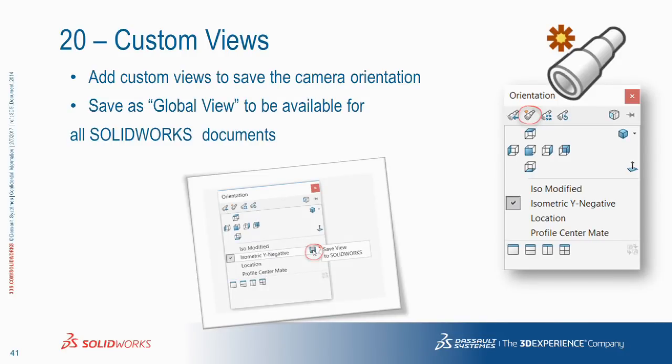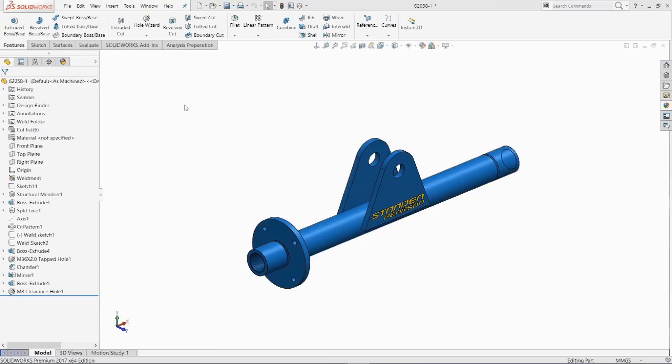Custom views. You orient your model, and then you want to be able to get back to that same orientation. You can add a saved view, a custom view, okay? And the way you do that is just basically hitting the space bar from the orientation box, picking that up, and clicking the Add New View button, all right?